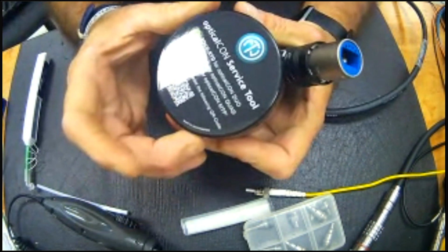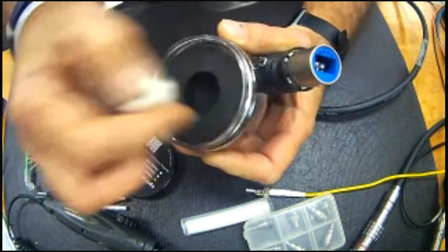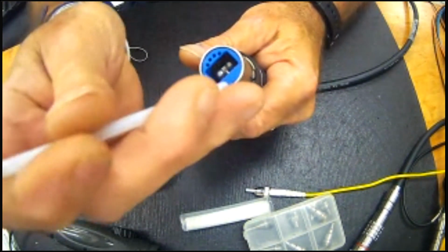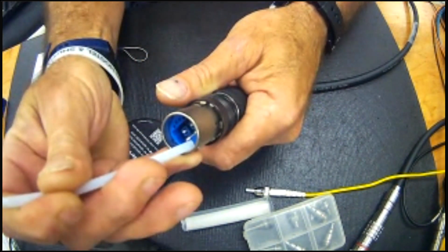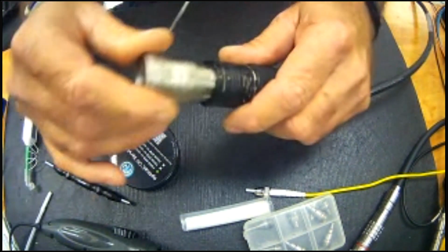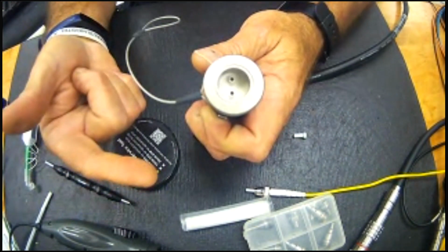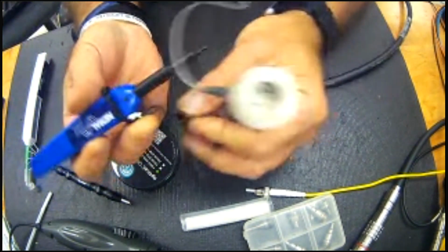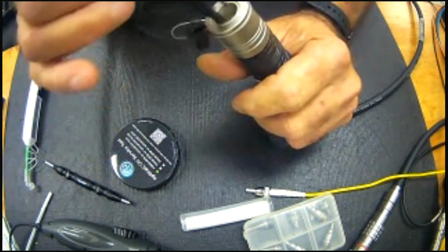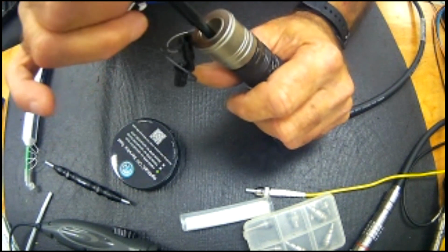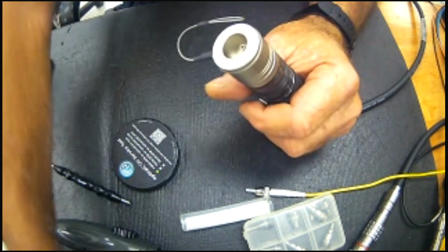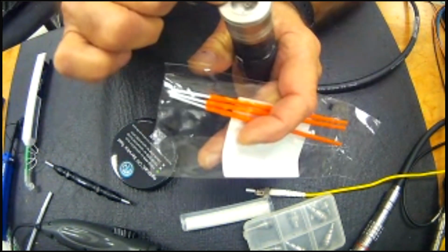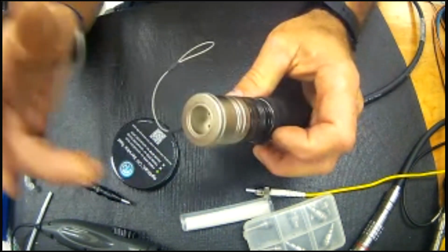Neutrik does make a small retainer adapter that will actually retract this, just like you saw me do, by pressing this down to expose the two contacts. It basically snaps on and gives you a tube. Now, what you do with that tube, well, you have to stick a one-click cleaner in that you've removed the tip from, that basically only has the smaller portion that goes down inside, snap, snap. Or you could use specialty stickler tubes that were actually made to go through small alignment sleeves for LCs.